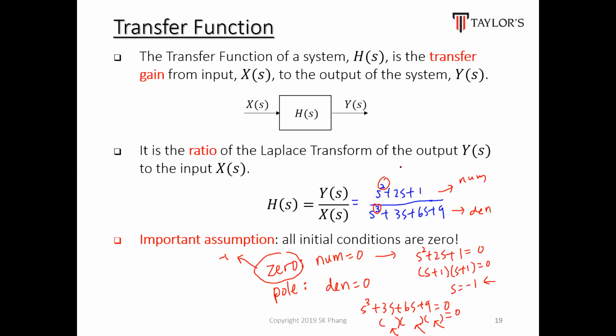When your power is 2, then you have 2, either zeros or poles. If it's the numerator, then it's 2 zeros. If it's the denominator, then it's poles. So in this case, if you look at this example again, I actually gave quite a bad example because both are s equals -1. They are actually 2 zeros, and both zeros are at -1. You have to write it this way. Both zeros are at -1.